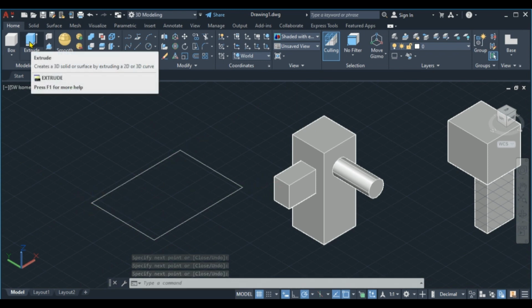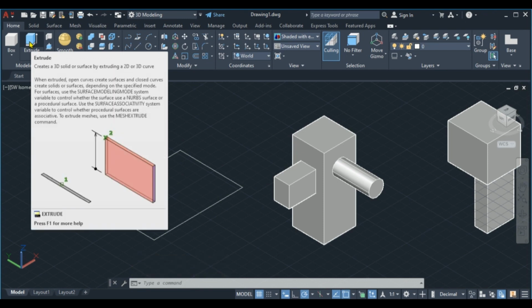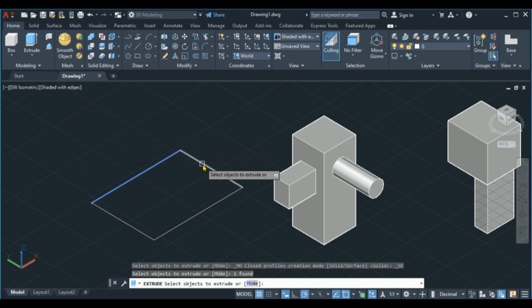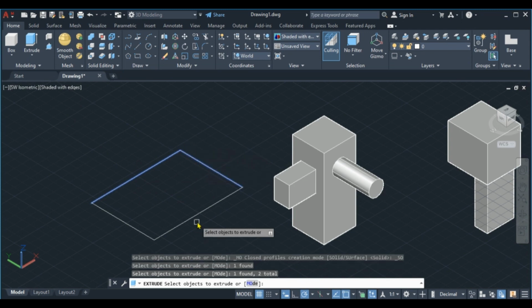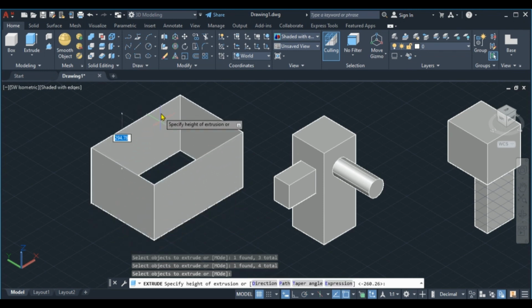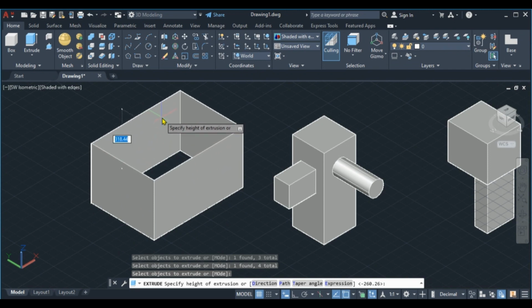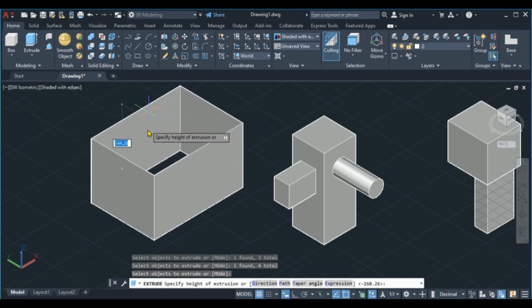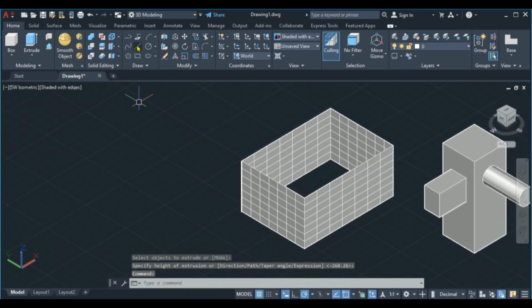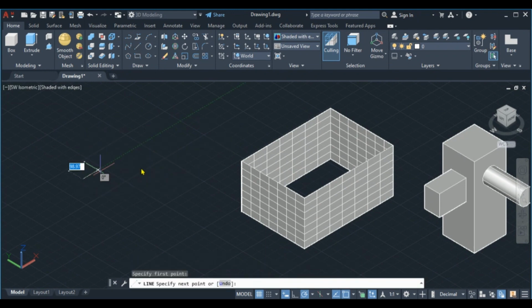I want to show you something because extrusion is always restricted to something that is developed for the right shape. So if I click here, it's actually selecting the individual line. Why? Because I did it using the line command. Okay, so this is how, when you have a line, you extrude with the line, not the shape. So even though you can use a line to draw on the AutoCAD model, you would have to now join the line so you can have a solid extrusion.